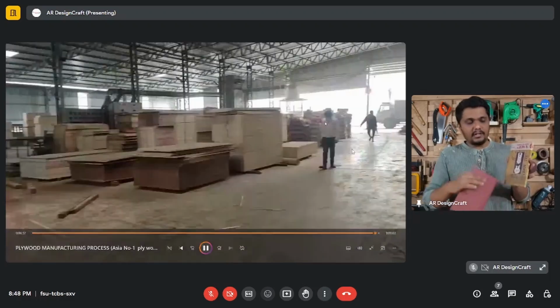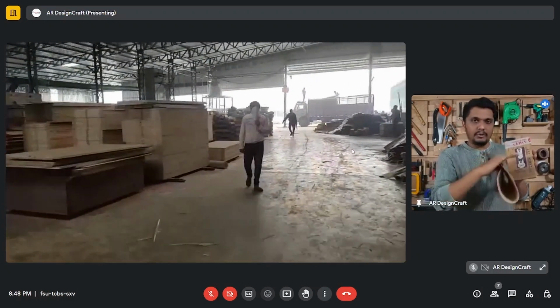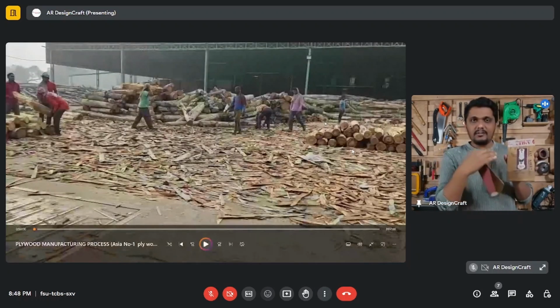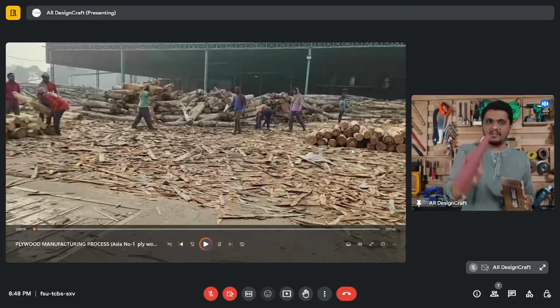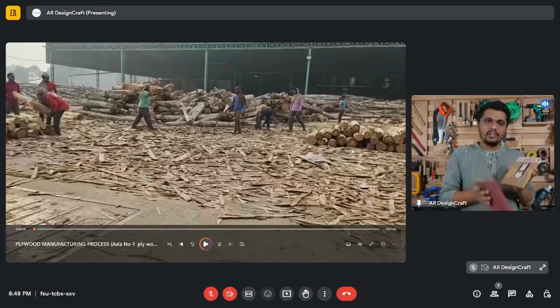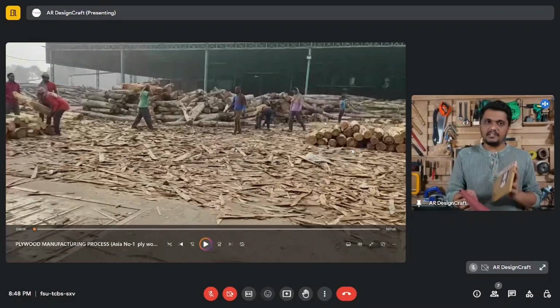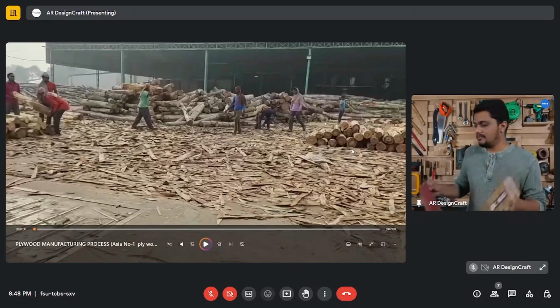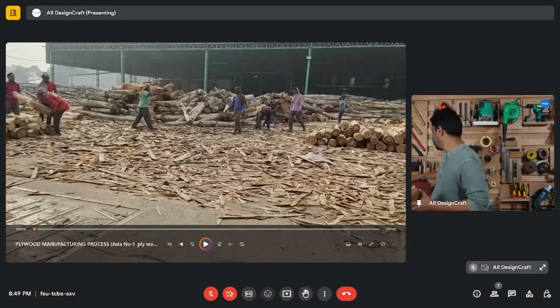ऐसे सैंड करोगे तो this will become smooth. All the undulations, roughness, all those things will go. So this is a sanding paper. वो मशीन के अंदर बड़ा रहता है, this is छोटा है. ठीक है, तो it will sand both the sides simultaneously. ठीक है, तो you will get a nice smooth finish जो दिखने में अच्छा लगेगा.